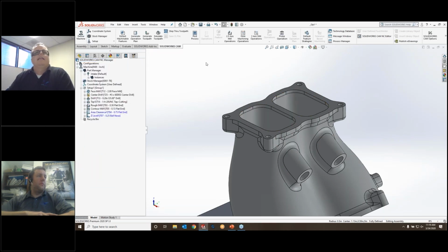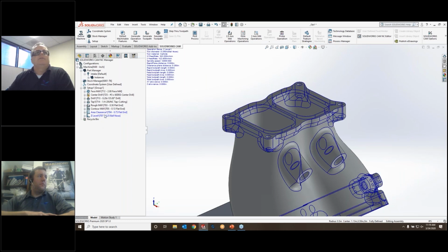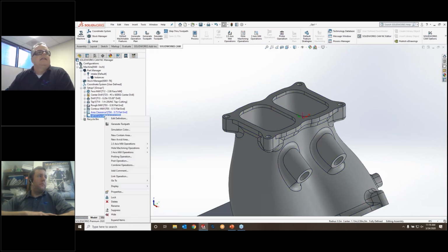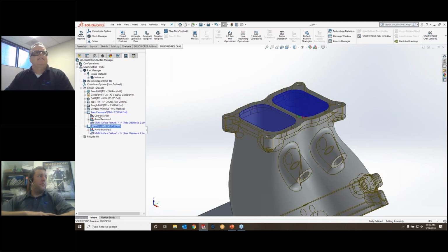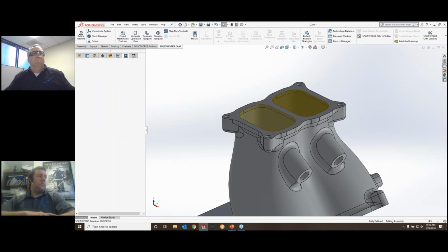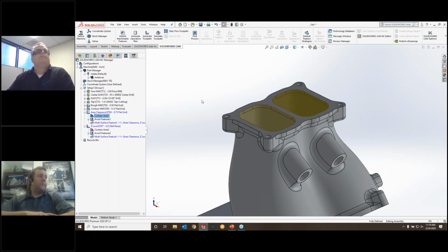I just hit OK here, and now I have that. And then the same for the Z level, right? I can set that all up inside here. Right click, then I can go through and edit the definition and do the same. I can insert it under a void area, or because I'm inside the same file here, I can just take that same control, that contain area control, and drag it and then drop it down inside there.